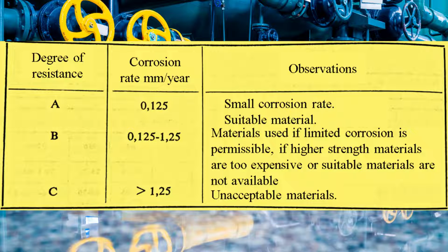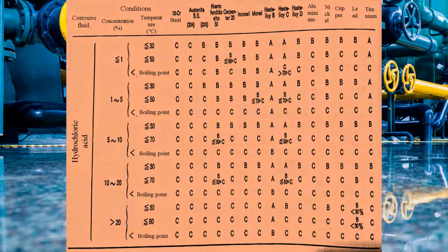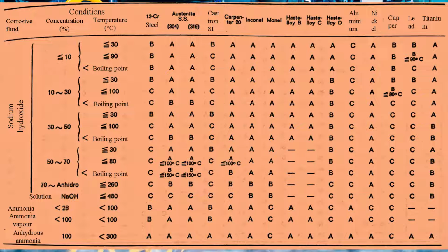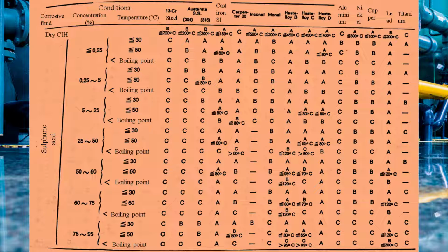As there is no material resistant to corrosion of all fluids, it is necessary to use combined materials, and their choice will depend on the environment in which they will work. Here, we can see a guide to corrosion-resistant materials without being an exact recommendation, because the choice of a material depends on the service conditions, which can alter the resistance characteristics of the material. Therefore, when choosing a material, it must be subjected to experimental tests.